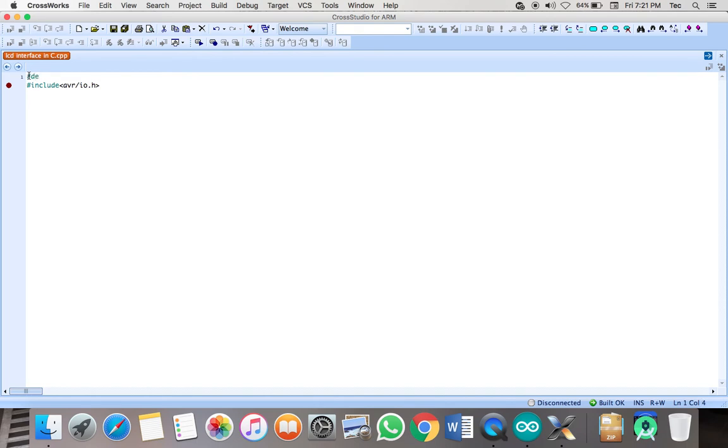Okay, then we say define F_CPU, and in this case our CPU is running at 8 million, or 8 megahertz if you want, so we're going to call it 8 million UL, like that. So we have defined our system clock.